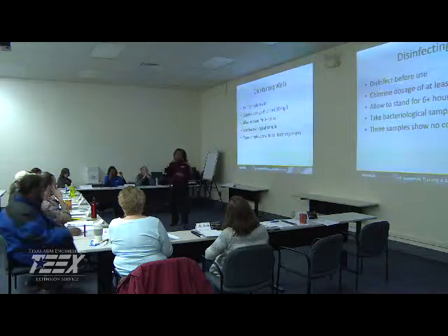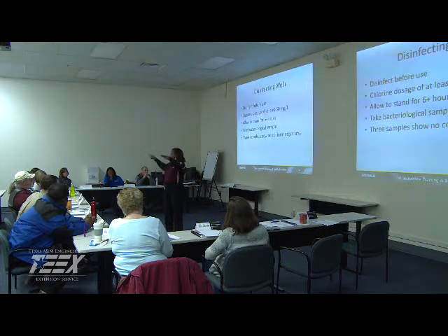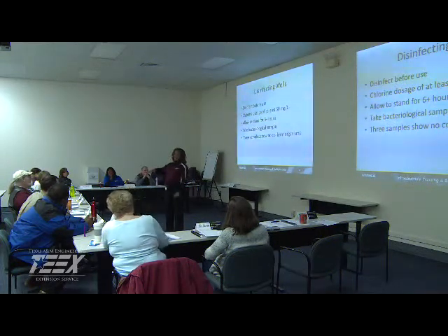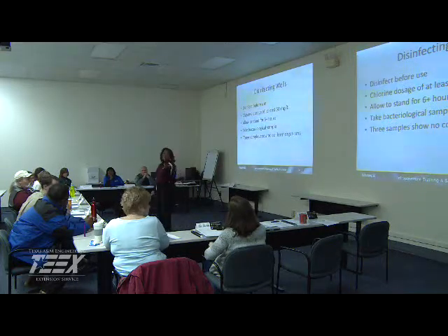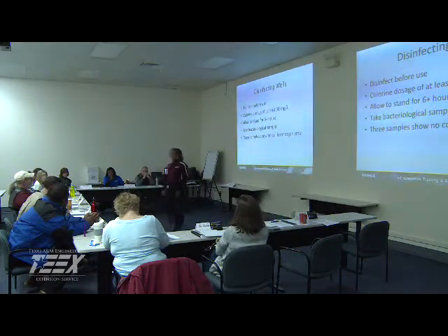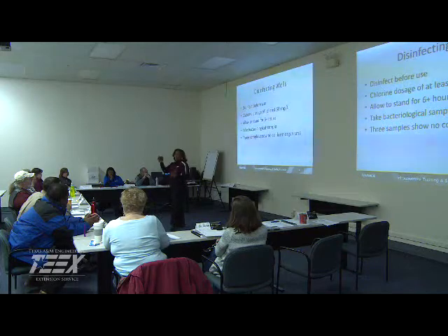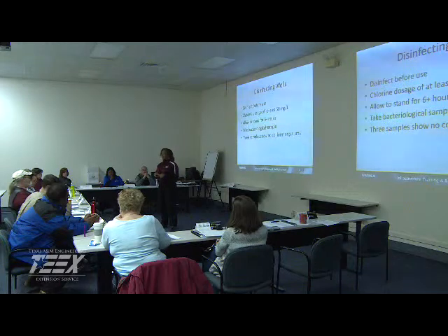Yeah, and that's interesting because disinfection is dependent on pH. And if your pH is high and you're adding something that is acidic that works best at a pH of 4, then you're going to have to use a higher dosage, absolutely. Well, he just said your pH were high. He's a surface water, shallow person. Unconfined aquifers and confined aquifers have high pH. Okay, got you. So looking at the chemistry, the characteristics, the quality of the water will affect your disinfection. If we have a deep well, then we have a high pH, and we have issues with the chlorine. So if we do a shallow well, it's really good.